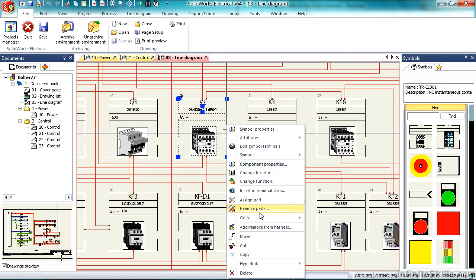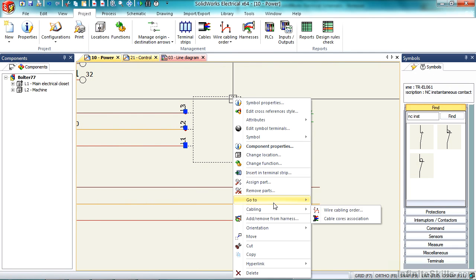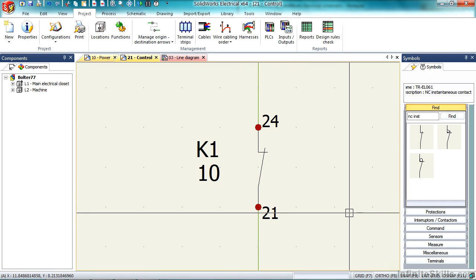You can also right-click any symbol and see the other off-page references hyperlinked right to it. Now I can go to the second reference, and there it is. And then I can go to the other schematic sheet. These also carry through when you output files as PDF. If you double-click the symbol, the hyperlink will bring you automatically to that location in the PDF file.